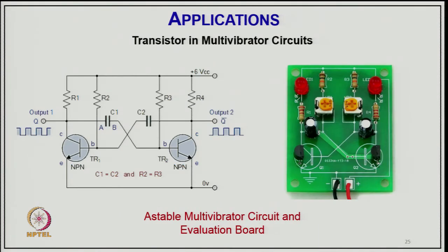And the third is the astable multivibrator, from which you can get a frequency which is decided by your RC network. Even if you want a variable frequency output, you can attain that from this, and you do not have to give any input. It is self-oscillating at a given frequency, which you decide by the design of these components, like the RC components here.